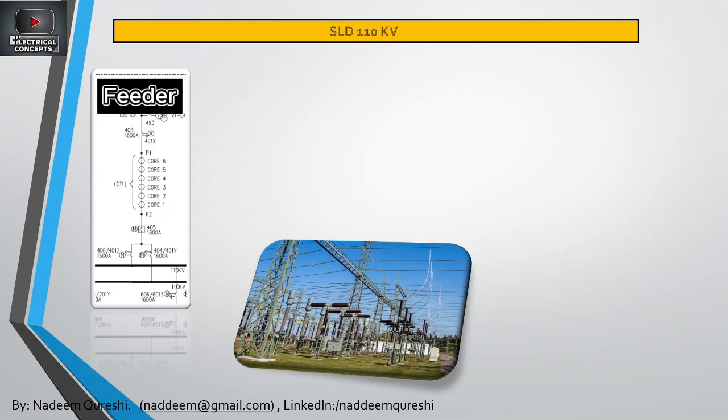Now this is a single line diagram of one bay which we discussed before. Here you can see some devices. I hope you remember from my previous video, the main devices are circuit breaker, disconnector, earthing switch, CT and VT. Can anybody tell what the operable devices are, the devices which can change their position, open and close? What are those devices?